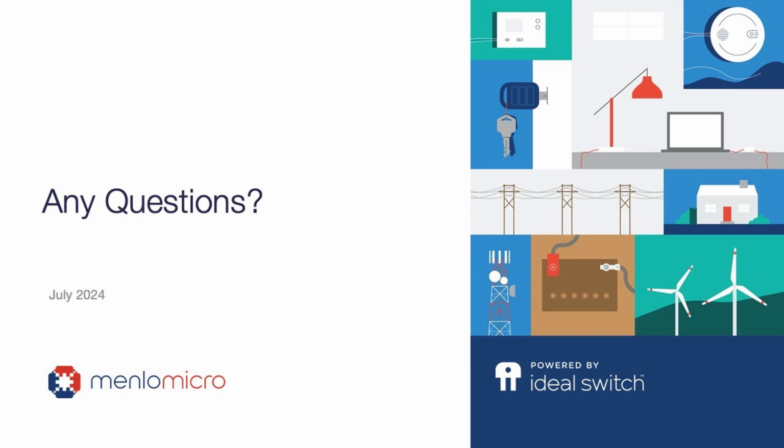Thank you. All right, Tom, next one here in the queue. This person is asking, for the MEMS switches, are there any internal ESD protection? So for some MEMS switches, there are ESD handling built in. For Menlo Micro, we do have some products with the ESD protection built in, but for our high power products, we do not.